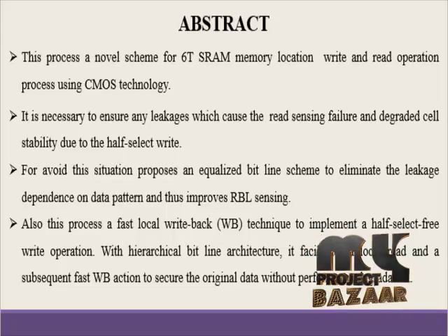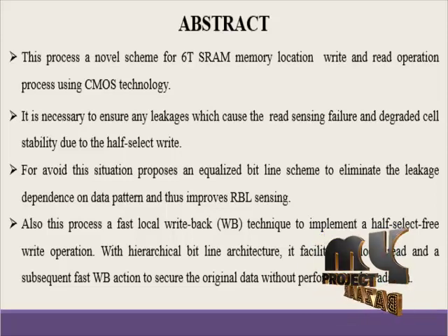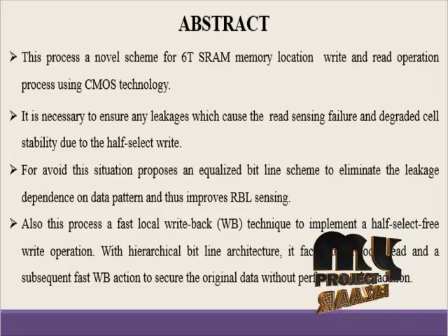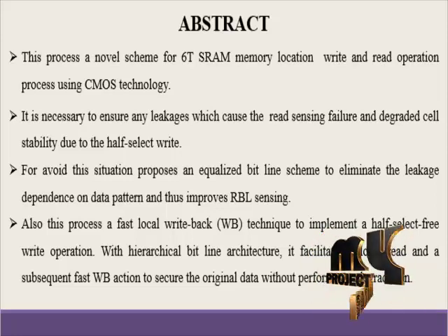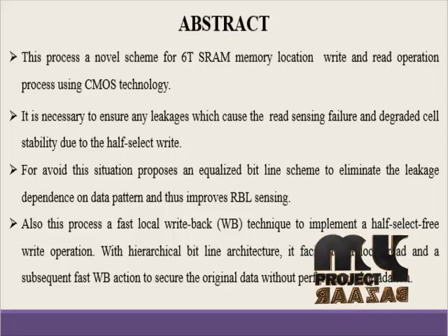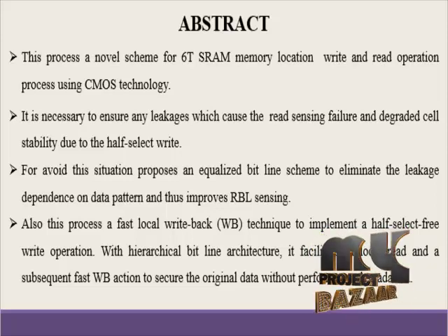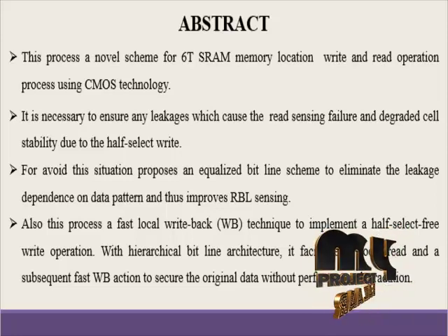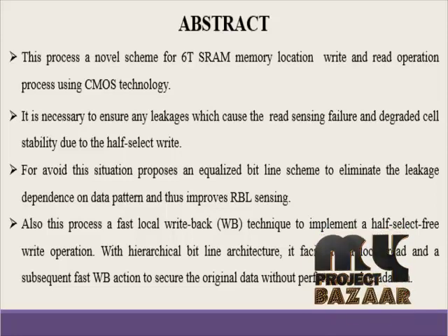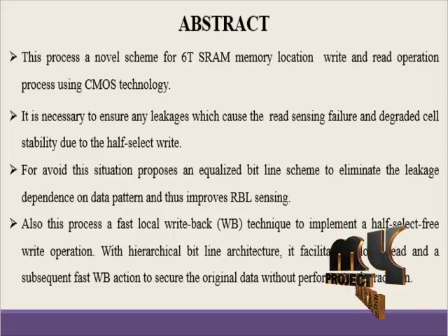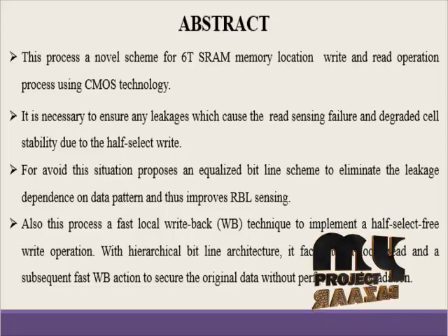some cells process. The voltage for the 6T SRAM process is generated by a constant voltage source. Particularly, we require a small voltage for a large number of cells, to avoid degrading the stability and inactivation of cells on a column. So we are using two additional transistors to separate the read port and decouple the read path.